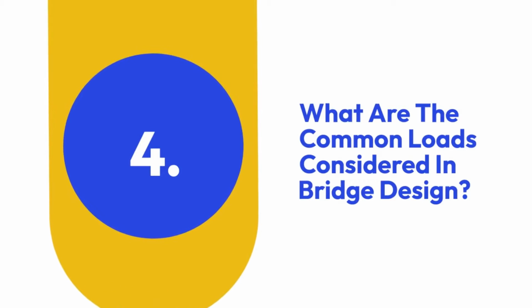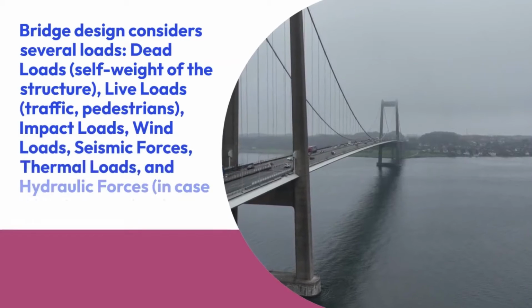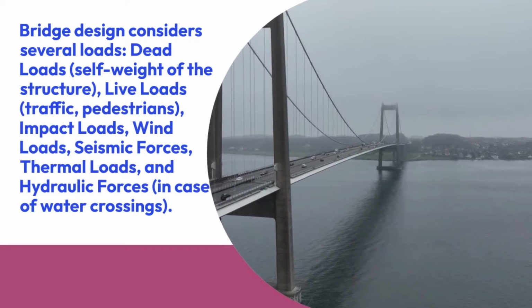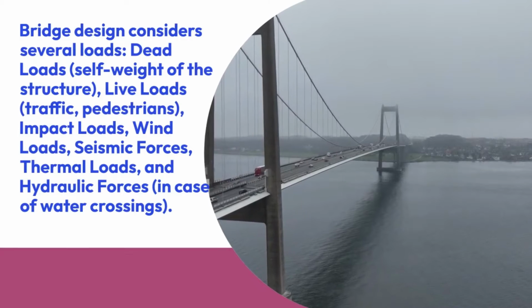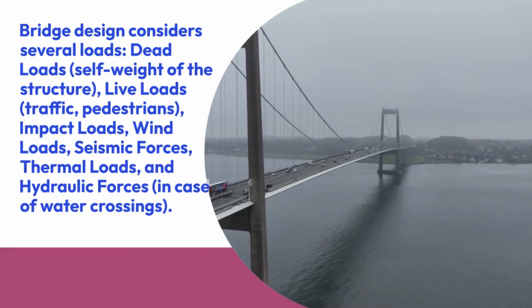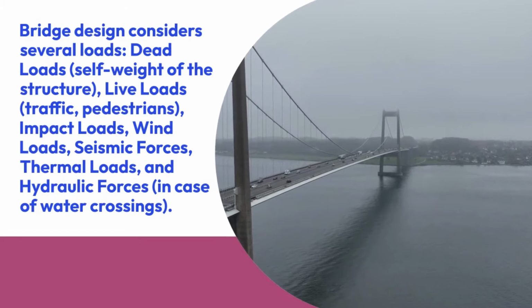4. What are the common loads considered in bridge design? Bridge design considers several loads: dead loads, self-weight of the structure, live loads, traffic, pedestrians, impact loads, wind loads, seismic forces, thermal loads, and hydraulic forces in case of water crossings.